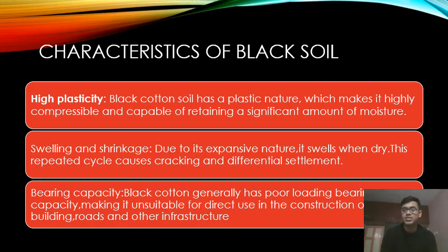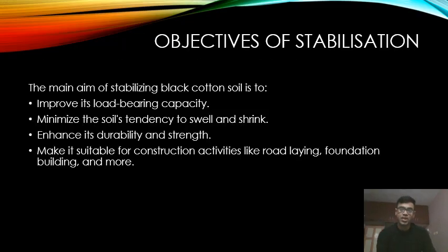So we need to address this issue before construction on the black cotton soil. The objective of this stabilization process is to improve its load bearing capacity, minimize the soil's tendency to swell and shrink, and enhance its durability and strength, making it suitable for construction activities like road laying, foundation building and more.